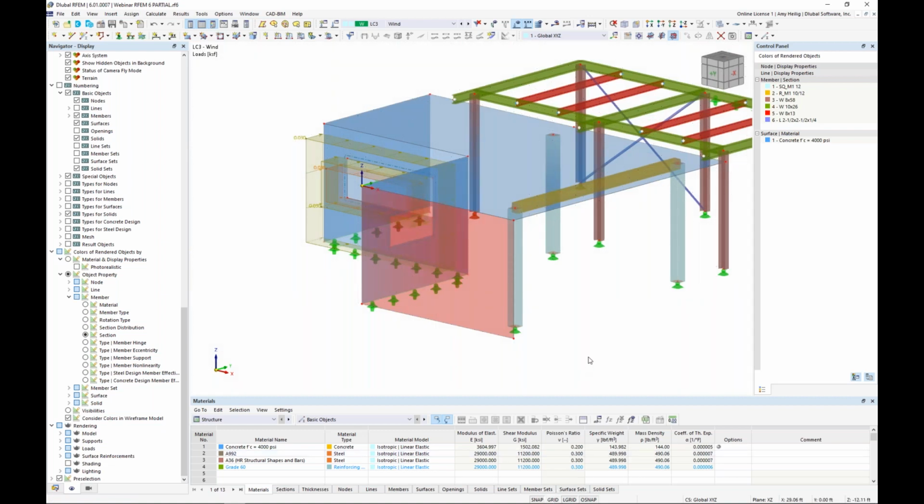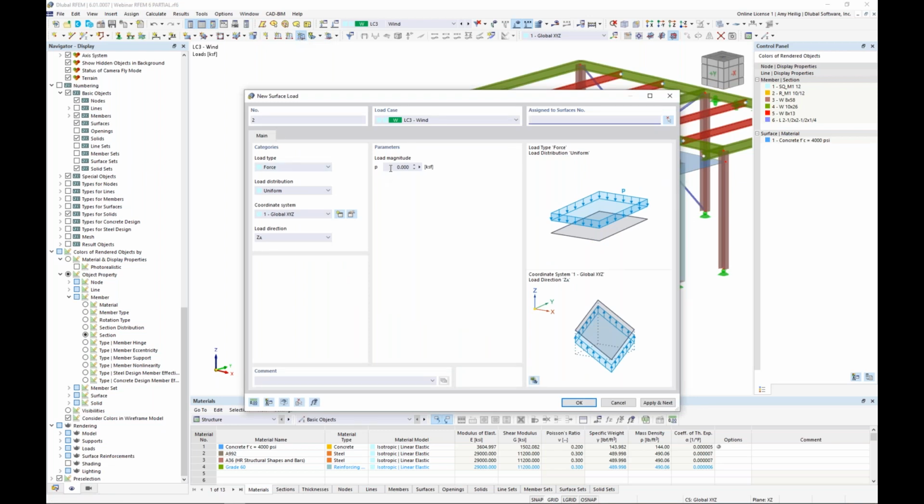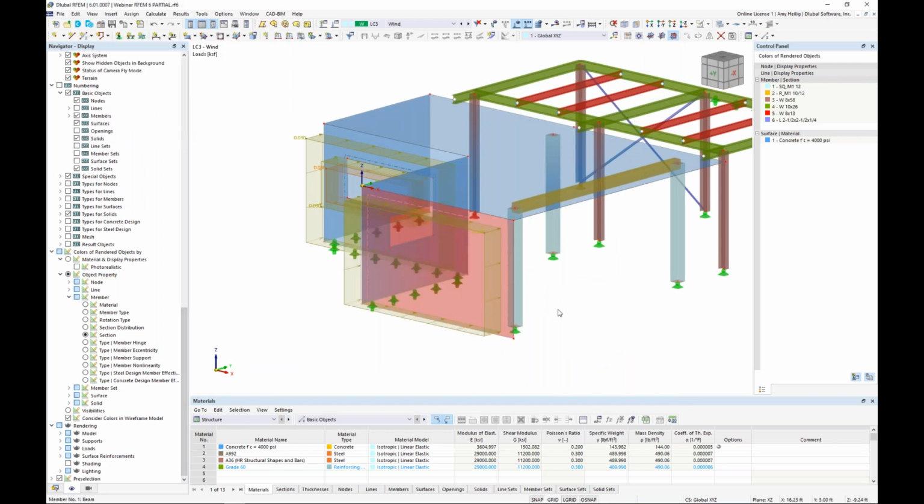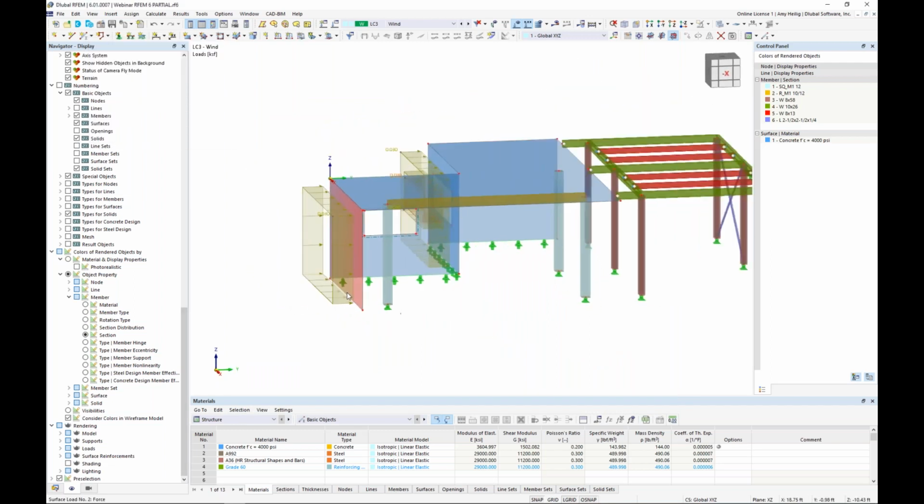Now again, I'm not adding any stiffness, material, nothing. It's really just used so that now I can go up here to my new surface load, apply a load magnitude of 0.03 in the global Y direction, just like what we saw with the previous wall before. I click OK, and I can now highlight this new surface, and we can see that load applied here.